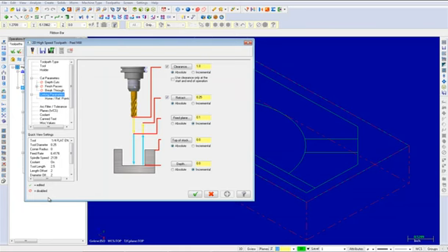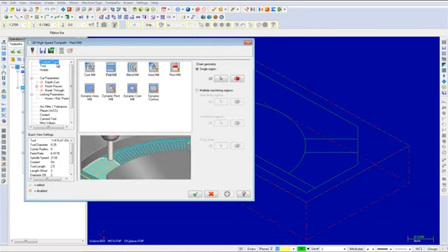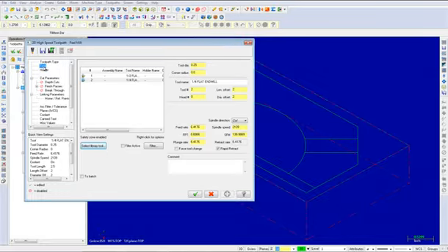From the tree view list, select the toolpath type page. You will notice that the peel mill is already selected. From the tree view list, choose Tool. Again, select the 1/4 inch flat end mill and input the following comment: machine the slot. Once the comment has been entered, choose the Cut Parameters page.